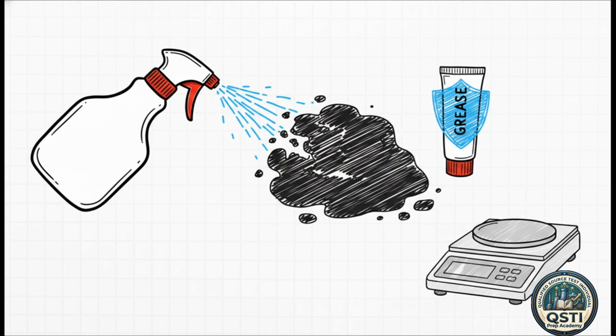You have to use TCE. That's 1,1,1-trichloroethane, instead of the standard acetone used in other methods. Acetone just won't cut it for dissolving asphalt. But here's the kicker. You actually have to run TCE blanks before field use to ensure the residue in the solvent itself is incredibly low. The standard demands reagent-grade TCE with less than or equal to 0.001% residue.